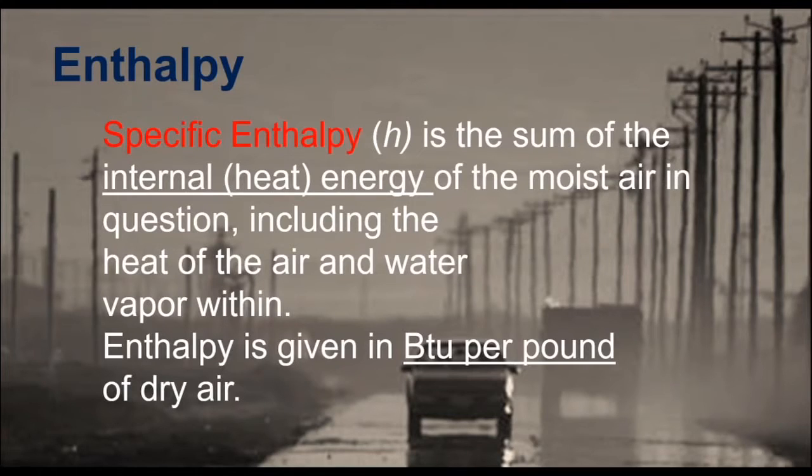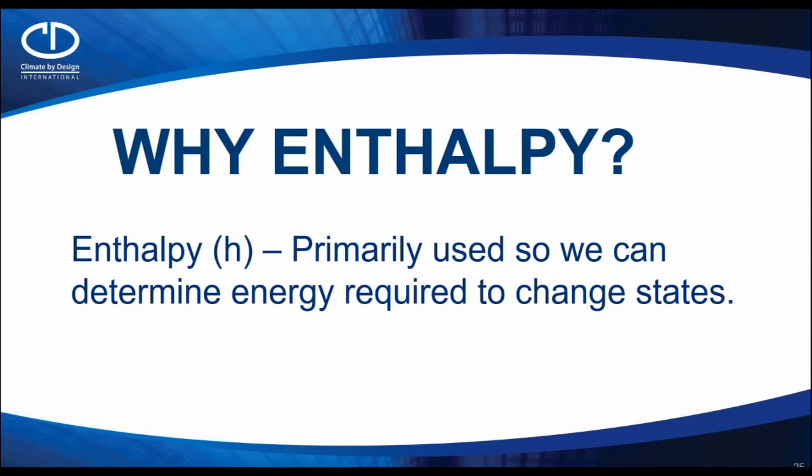Let's discuss enthalpy. A specific enthalpy is the sum of the internal heat energy of the moisture in air in question. It's both the heat of the air and the water vapor within. And enthalpy is going to be discussed or used in terms of BTUs per pound of dry air. Why do we use enthalpy? So that we can determine energy required to change states.